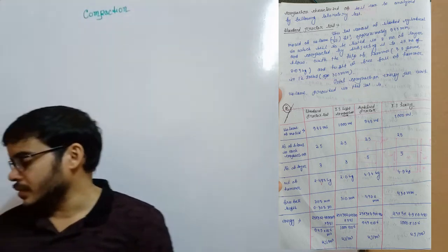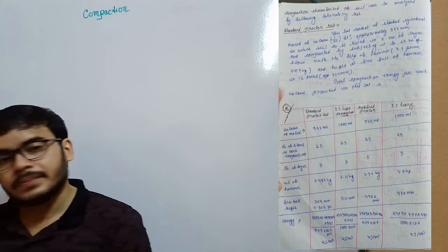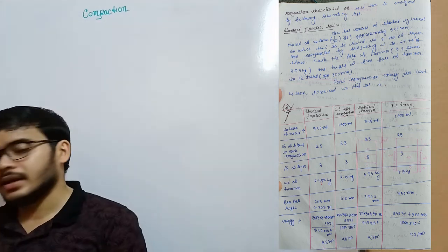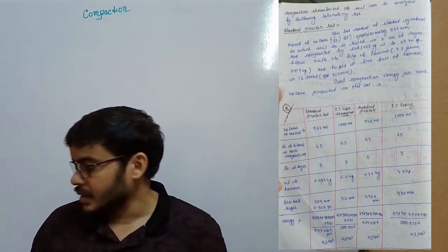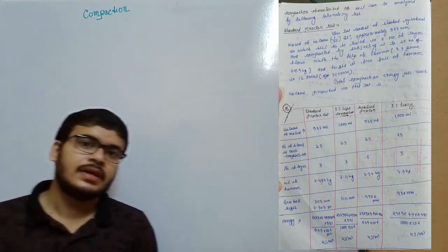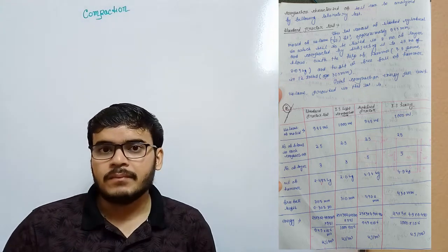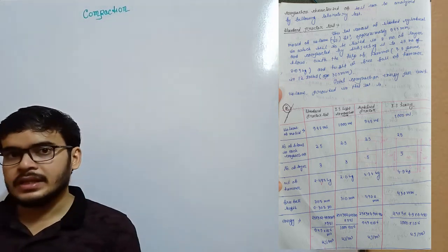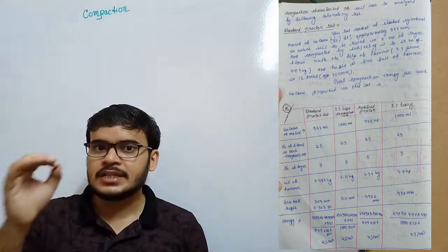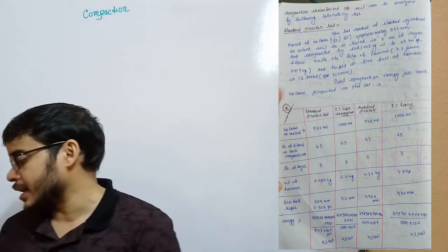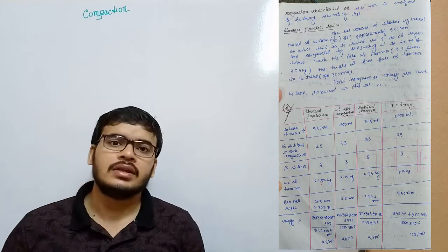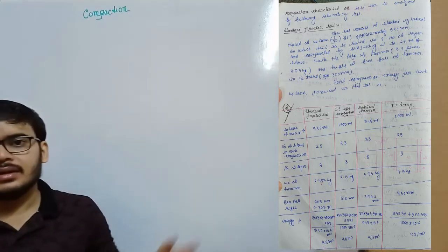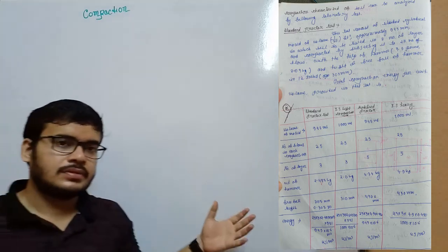And here we have volume of mold, number of blows of each compaction, number of layers, weight of hammer, free fall length and energy. So here the mold size is given, and in each layer the number of blows should be 25, and we have to fill the mold in 3 steps. In each step we have to hammer the soil 25 times. So complete the table here, there is nothing to describe.